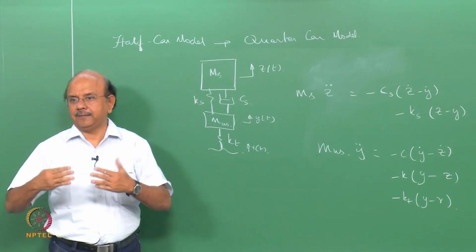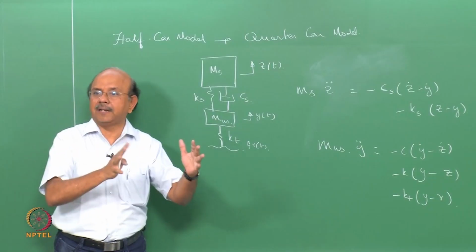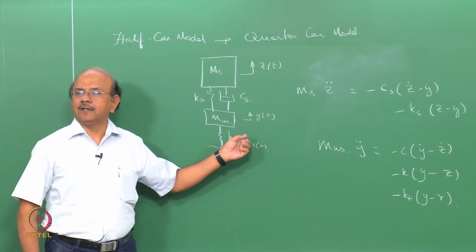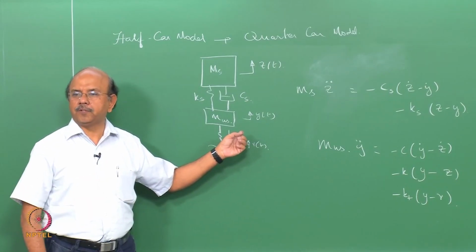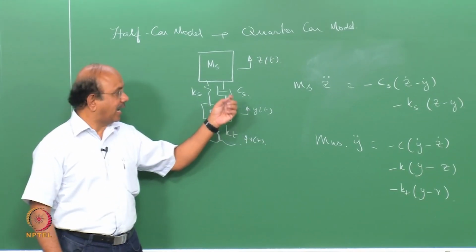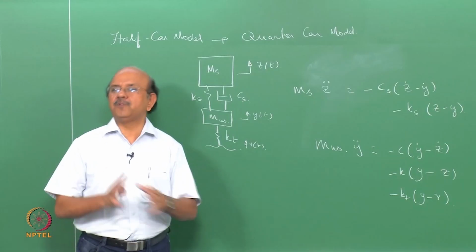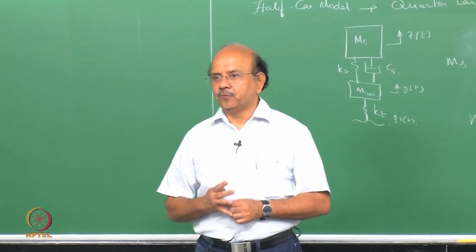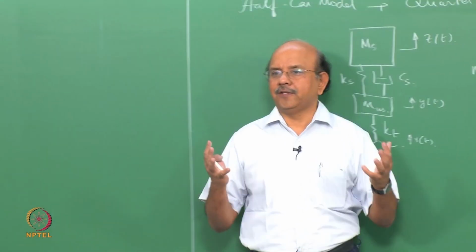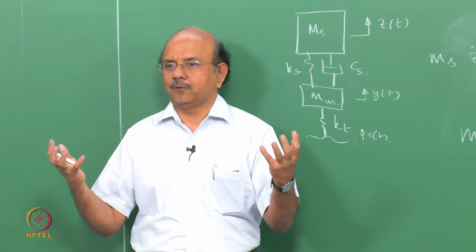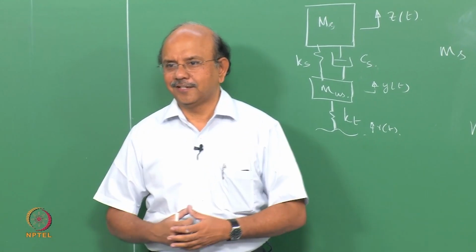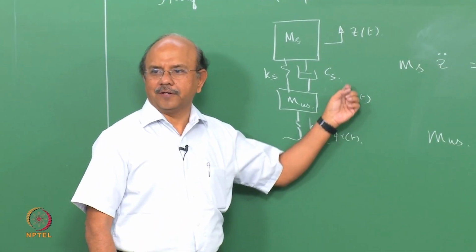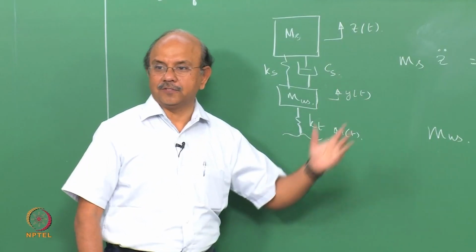It's a very highly damped system, but still it's an underdamped system. We are going to see that the difference between the natural frequency of an undamped system and a damped system will be small. So when I want to calculate the natural frequencies, which every mechanical engineer has such a good hold of, it's very easy to calculate the natural frequency even if I don't have an undamped system.